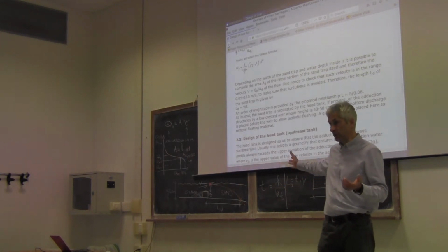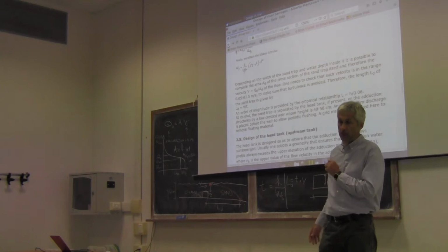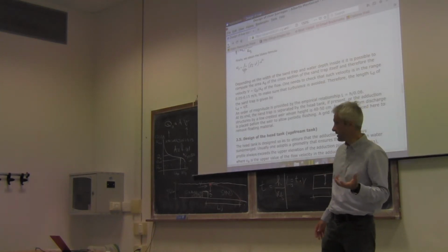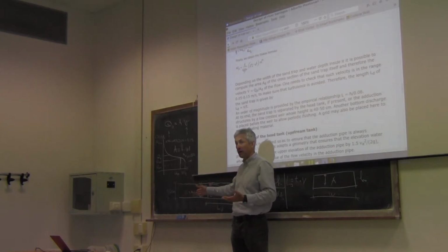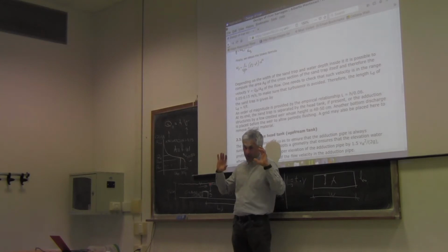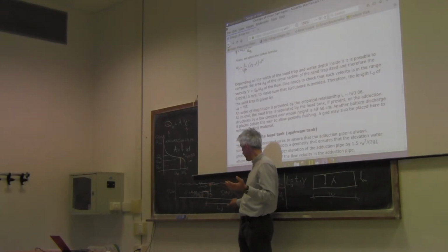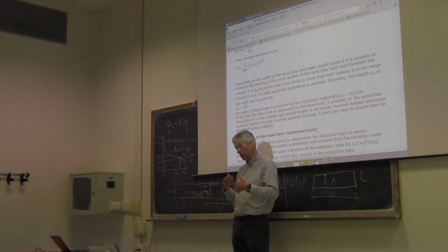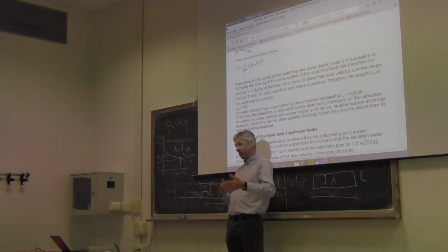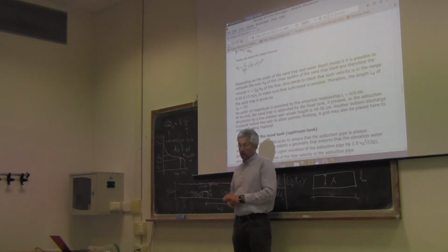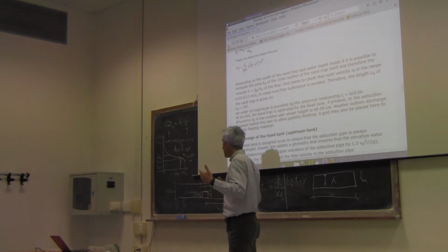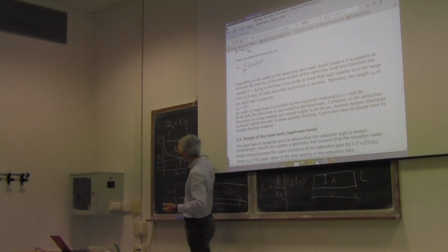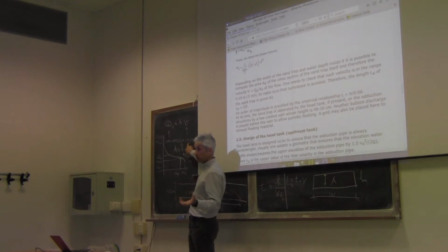In every computation that we make, there is uncertainty, but in this case in particular, there is a relevant uncertainty. You understand why? We are talking about an ideal particle that travels from the free surface and without suffering any impact from turbulence, then goes down along the floor. But if you also have some turbulence, of course, it's not so easy, because the particle with turbulence can remain suspended. And therefore, of course, we make any possible effort to limit the velocity here in order to minimize